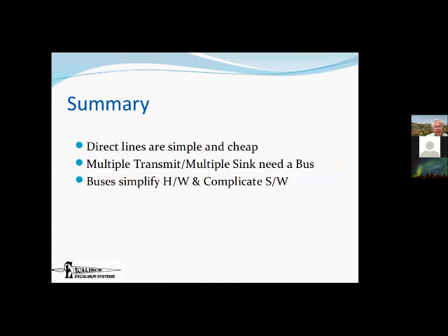On the other hand, if you've got multiple transmitters that have to talk to each other, that's not a good way to go. Fortunately, that's not what they needed on planes until recently. And now, newer planes that need more of that will use AFDX for the complex devices, but it will still use ARINC-429 and CAN bus, which in the avionics form is ARINC-825, for the simpler devices.